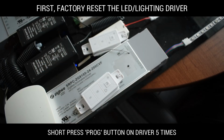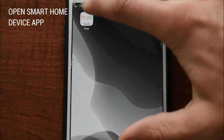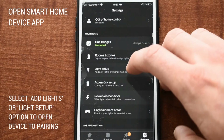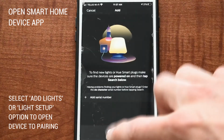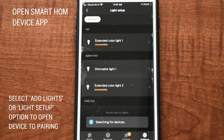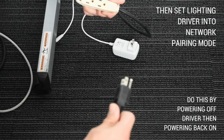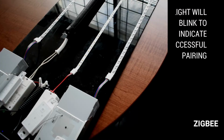First, factory reset the LED or lighting driver by pressing the program button 5 times. Then, open up the smart home device app and enable pairing for a lighting setup. As an example, it is shown here for the Philips Hue app. Then, set the driver into network pairing mode by powering the device off, then back on.